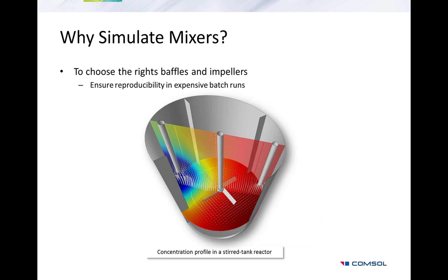Yet reality isn't a perfectly stirred tank reactor, and there are always the possibilities of dead zones or zones with little mixing, affecting the overall conversion and composition of the mixture. Here we see there is quite a lot of variation in the composition between the inlet and the outlet. Simulating a full model of the conditions in a possible reactor setup using baffle placement and impellers of a particular design will give you that much more confidence in the reproducibility of your mixture composition.